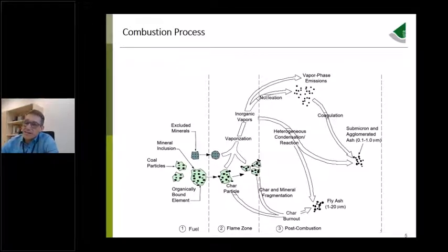Volatile elements evaporate into the gas phase, and the rather low volatile elements, which are mainly char and mineral fragmentations, stay in the grate zone and the grate ash and end up as rather coarse ash with rather larger particles.